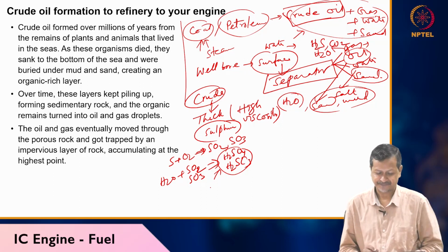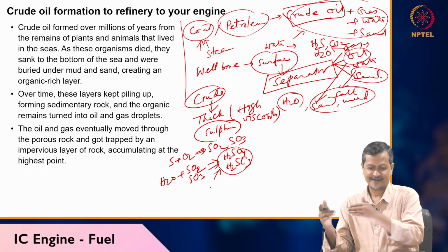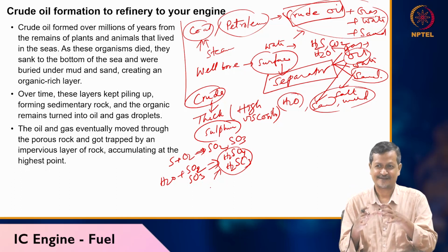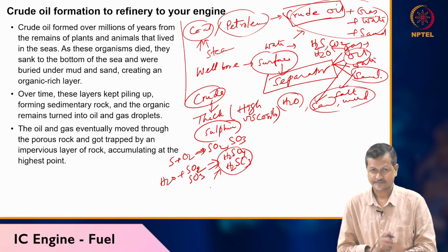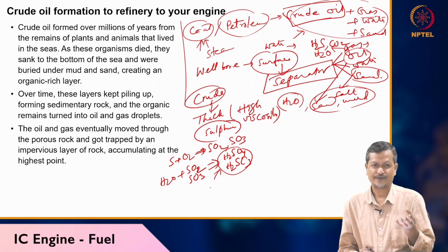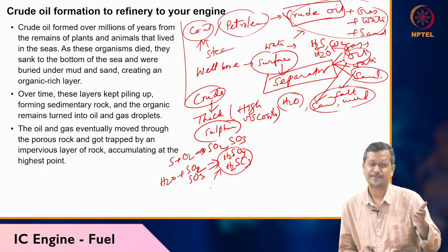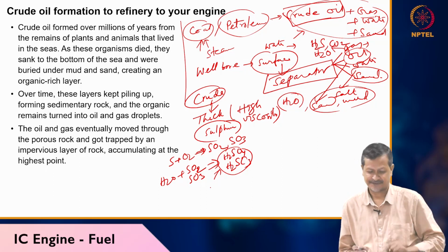Later we will discuss. So whenever you are getting crude oil from the wellbore, you have to remove all the particles, then finally you get a thick fluid crude oil. It has very little water, sulfur dioxide, hydrogen sulfide, all these things, okay. Now this thick fluid also you cannot put into your cylinder, so maybe you have to increase the temperature and change the viscosity, okay.